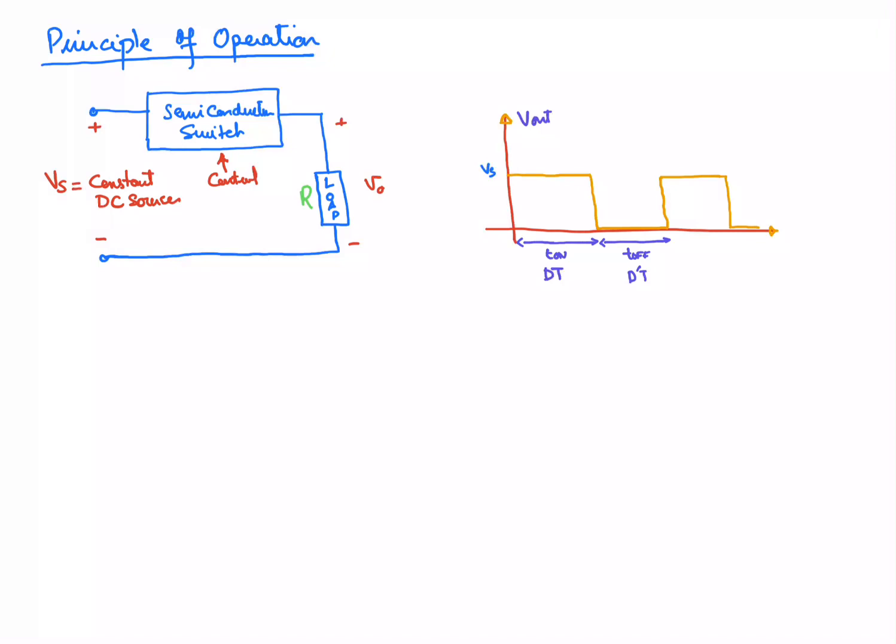So, let's suppose that the resistance is R. In the last video, we have seen that this switch is basically going to amplify. Whatever is the input voltage, when you turn on that switch, that will appear across the output. However, your control signal will be of a small voltage level, maybe 3 volt, 5 volt, 12 volt or 15 volt. Usually this is the voltage range for the control signal. But your output voltage level will be equal to your supply voltage if there is no voltage drop, right? But in the practical case, there will be a small voltage drop.